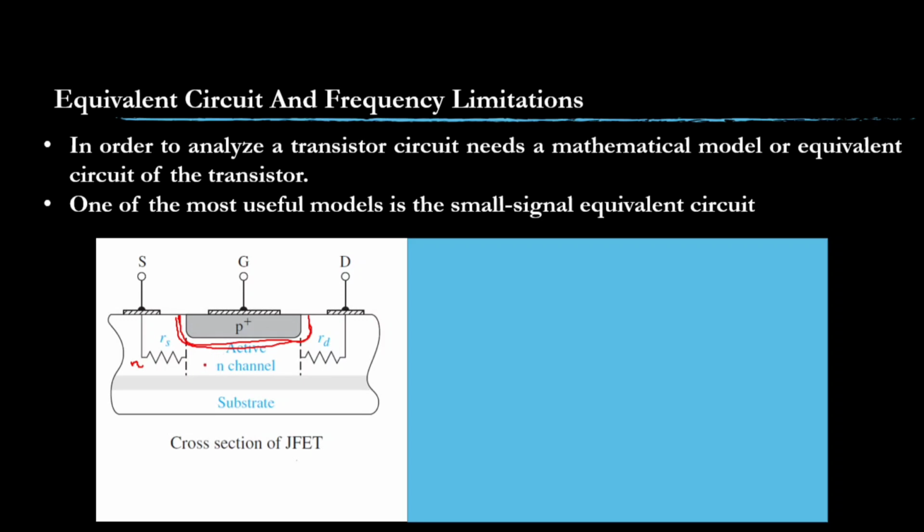The depletion region is completely depleted of charge carriers, and it introduces some capacitance, because either side of this depletion region has positive charges and negative charges. If positive and negative charges are separated apart by any medium, it offers some capacitance.